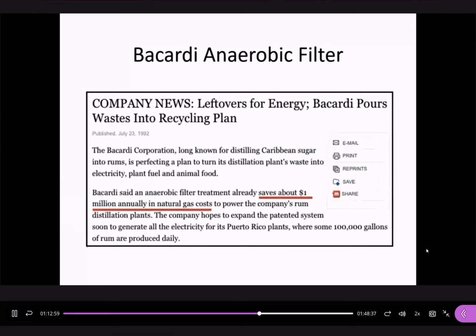So that's why nowadays we're talking about carbon neutral or carbon negative wastewater treatment. Now wastewater treatment is consuming energy, right? But now many people are working to make wastewater a source of energy. It could be easy if the organic strength is high, like industrial wastewater or sludge; you can produce a lot of energy from that type of wastewater. But for municipal wastewater, organic strength is low, COD a few hundred, right? So energy density could be low. So that is a challenge.